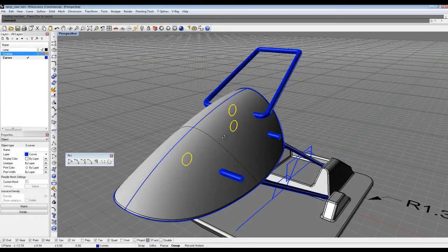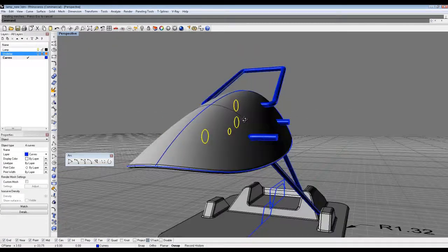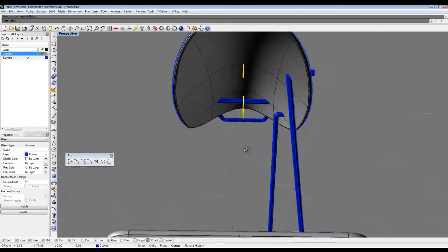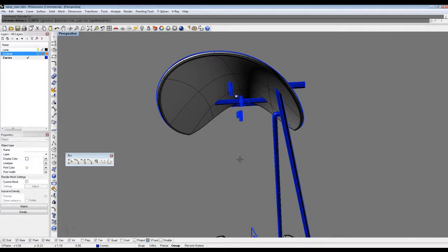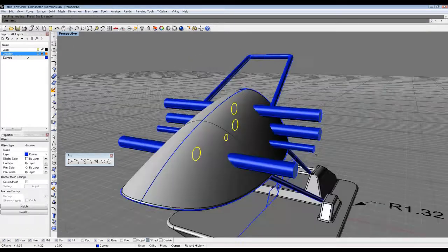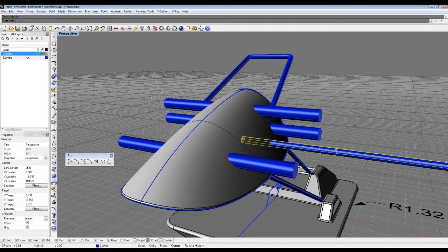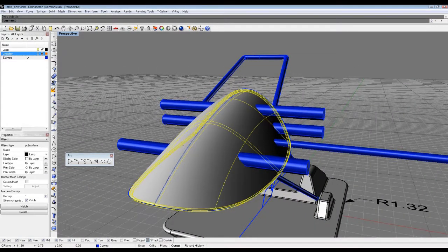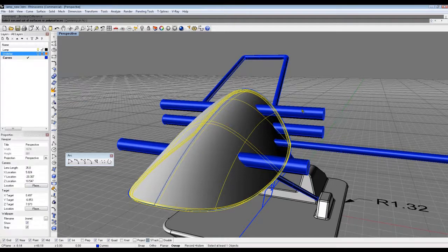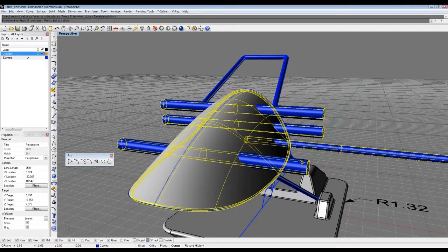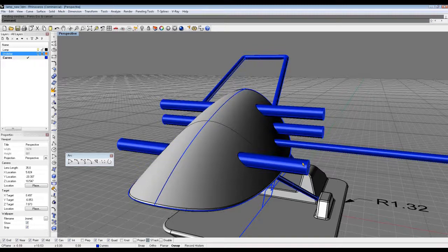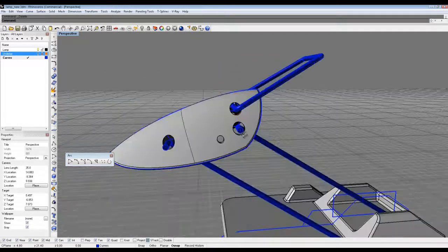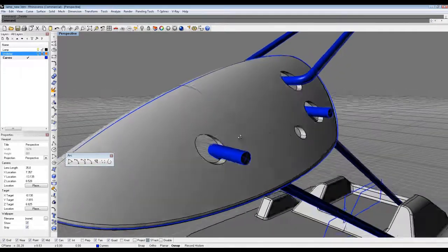So got one more thing to do to this lampshade, and that's to extrude it. Extrude the curves that are here, and these are going to act as Boolean operations on the lamp here. So we'll take the lamp itself, do a Boolean difference, and then we can delete those, and you can see now those are passing perfectly through the center.